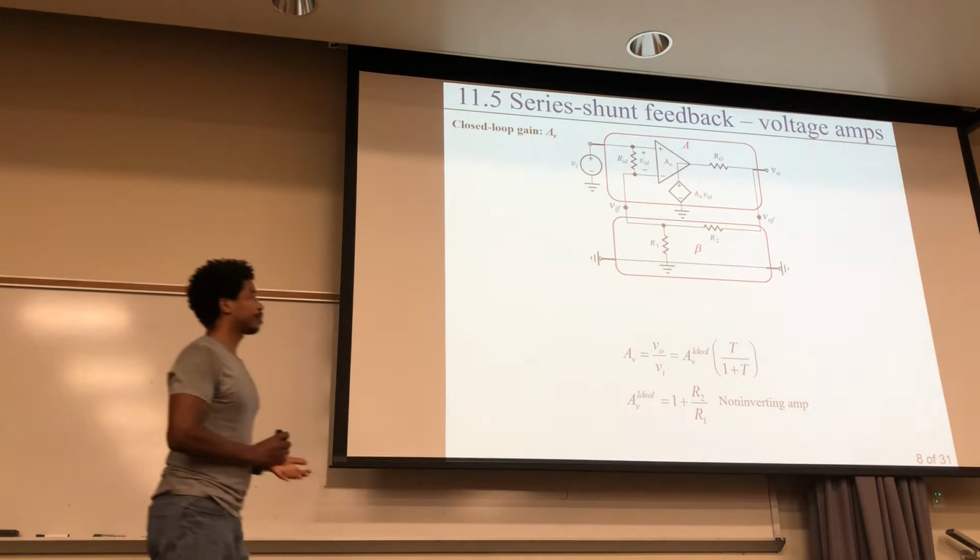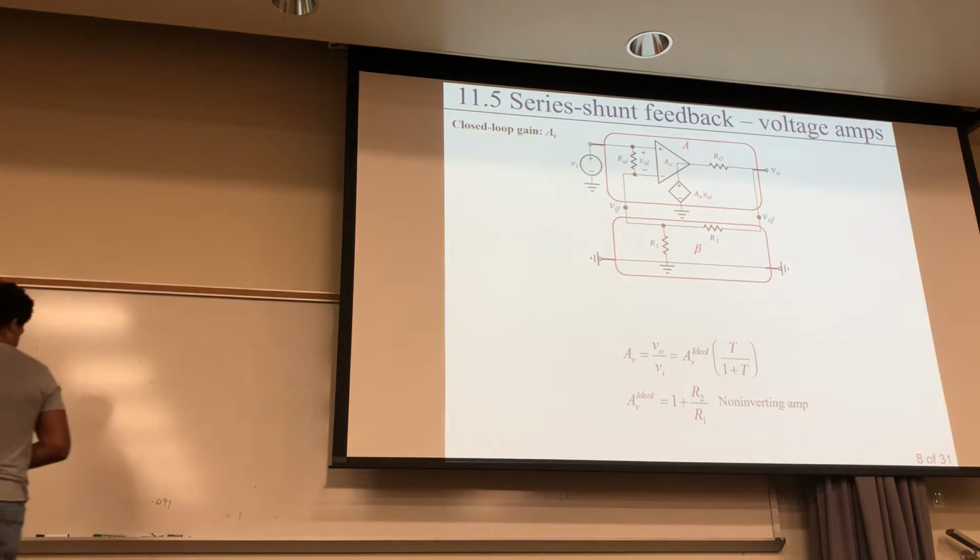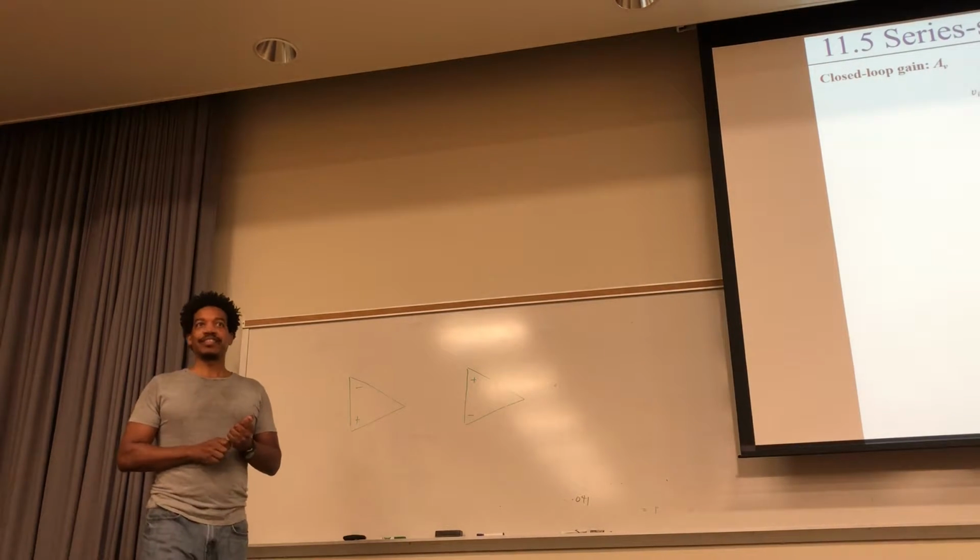Okay. And another way to think about it is, let's suppose we have an op amp right here, and we often see these signs there, right? Sometimes you'll see the sign like this. Sometimes you'll see the sign like this. But the math that we apply to this has been basically the same, right? So what's the significance of these signs right here when you apply it to a non-ideal op amp? Voltage rails. You can't go below your voltage sources. Inverter. Well, you can go below your voltage sources.